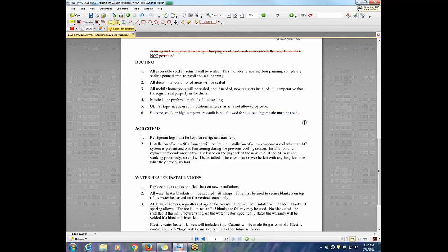He wanted every return air that you could get into, any return air duct, panning, or grill, sealed. This is an existing home. We are not building any ductwork. This is just existing ductwork, and this document says we want to seal everything we can reach. Again, this was a Mike Johnson thing that was put in there.